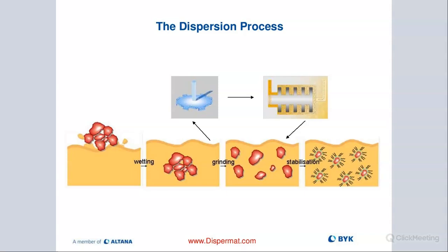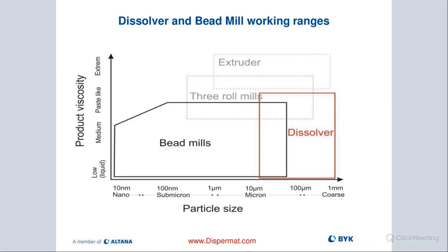If we go to the milling system before we actually achieve 10 to 20 microns of particle size, then we have a possibility of clogging our screens or dynamic gap in a mill, and that is not good. So we really want to bring down these agglomerates to the 10 to 20 micron aggregate size before we start the milling process, so we don't have any clogging issues with our mills.